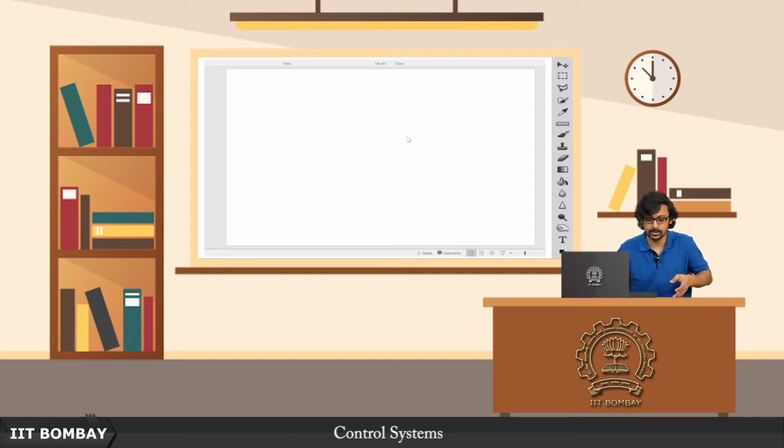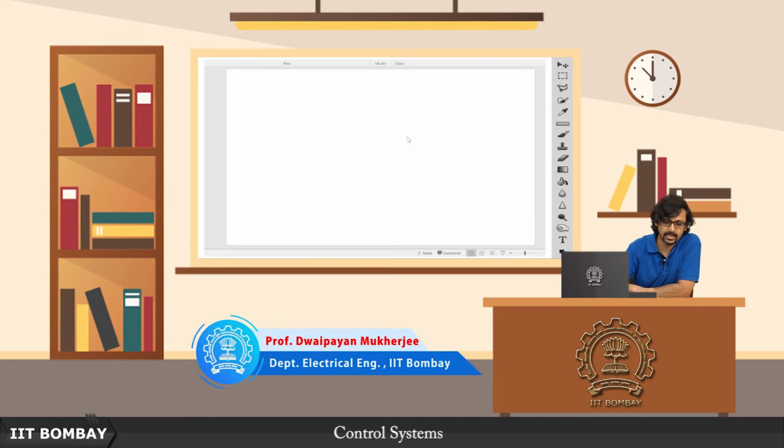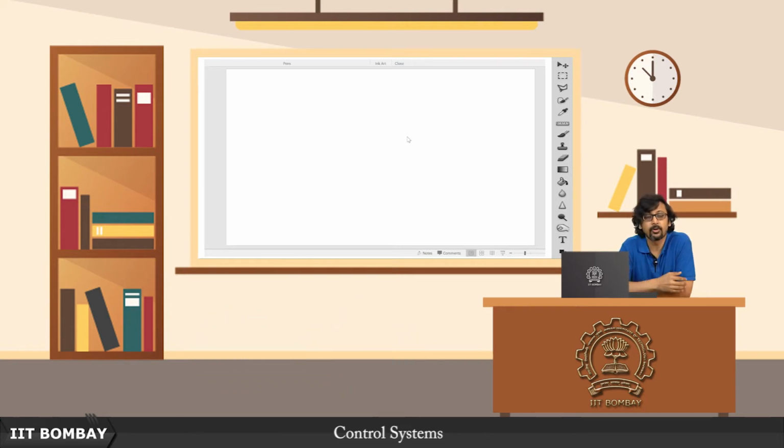Hello and welcome to another lecture on this course on control systems. In the previous lecture we have seen these two interesting transfer functions, namely the complementary sensitivity and the sensitivity functions, particularly for closed loop systems. Prior to that we saw that when you actually want to put an open loop transfer function into a closed loop configuration, then you have to consider at what stage you are going to drop off the additional poles and zeros so as to be able to approximate the overall system as a second order system, which will then bring to play all the things that we have learnt about the performance metrics of second order systems.